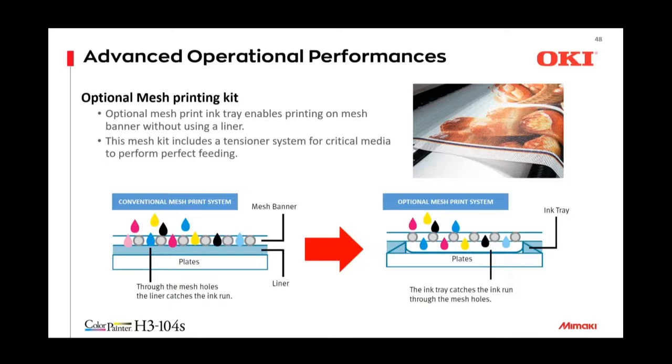If you had a mesh that was over 50% see-through, let's say only 40% media, 60% open, they said it could be a concern because the ink would build up too quickly and potentially go back onto the backside of the mesh. So it's not an entirely fixed solution. There are some restrictions regarding the mesh.